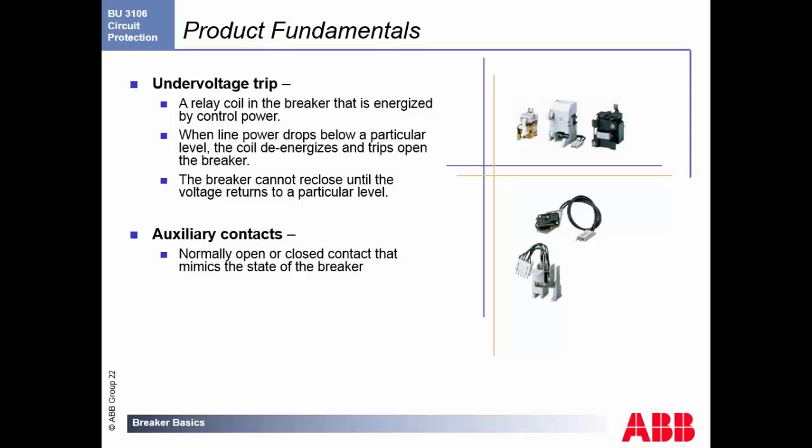You can have it done on automatic, say a time clock. So on a building that you want to shut down the breaker on, say, a Wednesday at 6 p.m., if you have a timer that can send out a 24-volt signal to our breaker, these auxiliary contacts will accept that, a dry contact closure, see that now you want to open the breaker, and it opens.